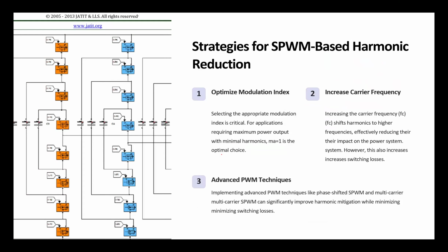It can easily be seen that a multi-level inverter would reduce the harmonics, and we know why: because we have multiple carriers trying to switch in multiple stages in our voltage, so it would mimic a better sinusoidal at the output. Is that clear?